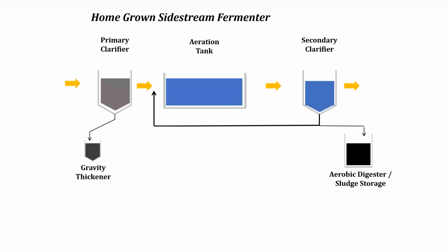Well, then I've got waste sludge in there. Waste sludge is the same thing that was in the aeration tank, so it's got the same kind of population blend. They're just old and cranky because I've taken them out of the action and am not feeding them anymore. So I want to turn that into a fermenter.